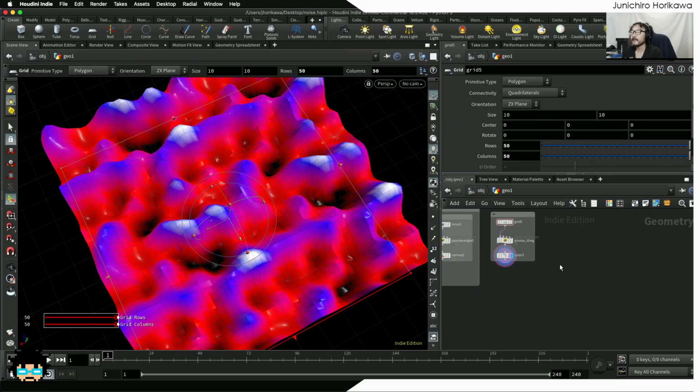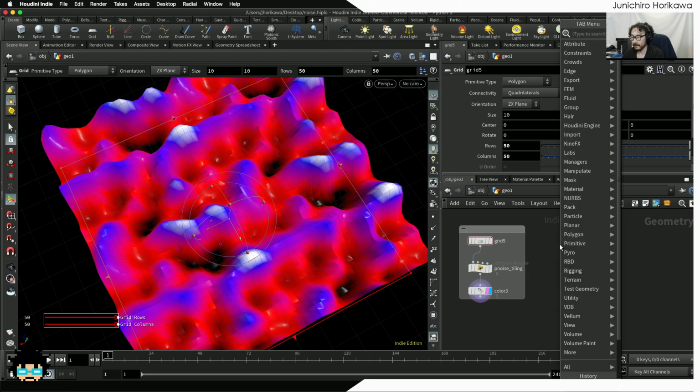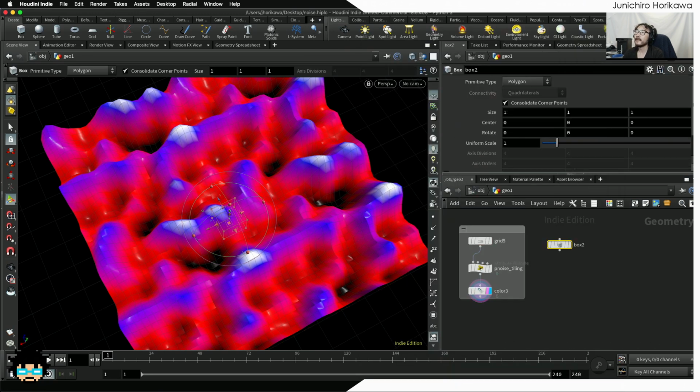Now, as an advanced exercise using this periodic noise, let's try to create a 3-dimensionally tiled pattern, which you can repetitively expand in X, Y, and Z direction as a 3-dimensional geometrical pattern. And to do that, I'm going to try to use a volume in this case. So first of all, I'm going to create a box as a base geometry, and let's set the size to 2.